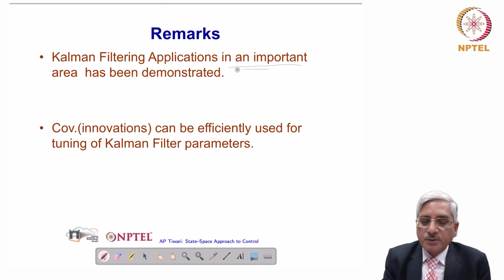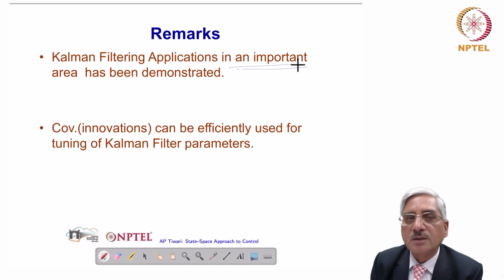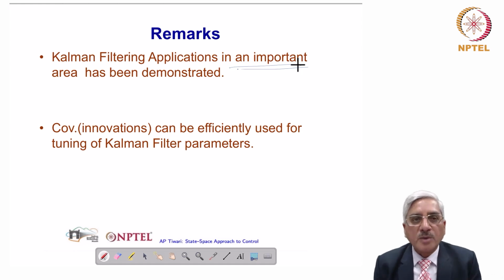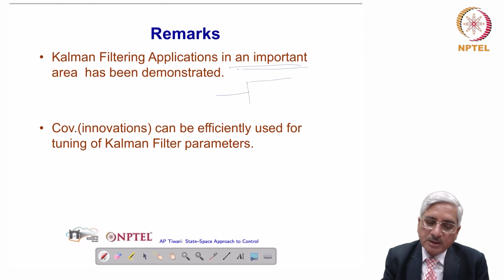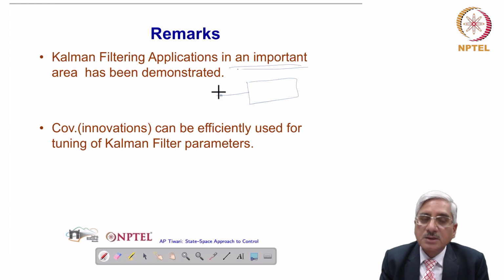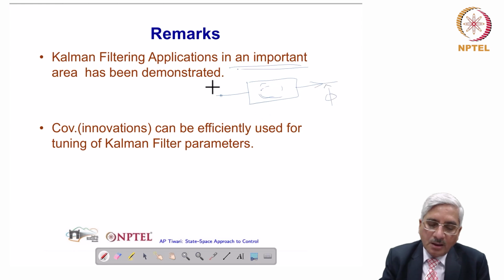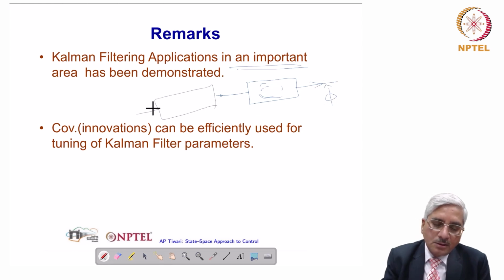So we have shown the application of Kalman filter for improvement of the response characteristic of the Vanadium SPND. What we meant is that we pick up the Vanadium SPND signal and compare it, inside the Kalman filter, to the computed Vanadium SPND signal. We correct and thereby we get phi hat. So this is the actual flux in the reactor. This is the Vanadium SPND along with its amplifier.